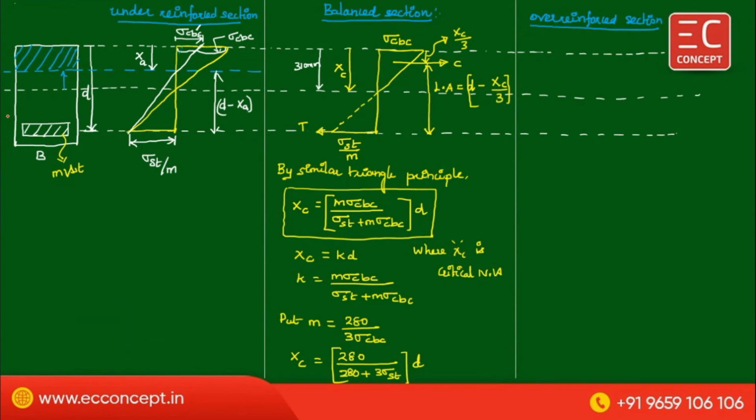So this is the neutral axis. The neutral axis shifts downward. This is the neutral axis somewhere here. Here the neutral axis shifts down from the original. Therefore now this entire area is the area of concrete for the over reinforced section.